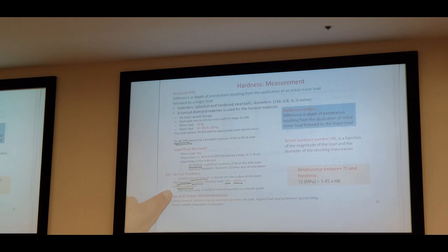Notice that here there is no minor load. I will show you the video, but a microscope or digital camera is used to determine the diameter of that indent.